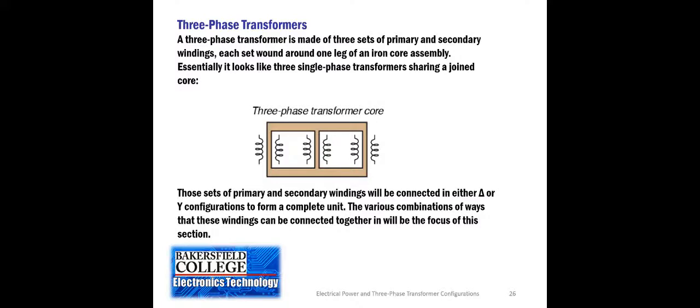One of the things that happens is that on a building transformer or one feeding an industrial plant, you often have the three-phase transformer all built together as one unit. So it has three sets of coils, three primaries and three secondaries. They share the same magnetic core because that helps make the transformer more efficient and it helps focus that magnetic energy a lot better.